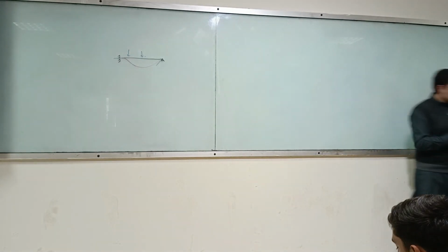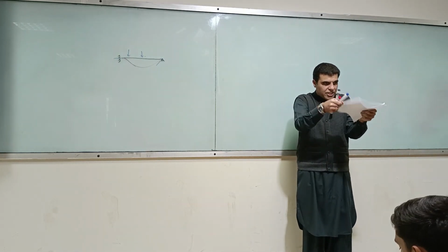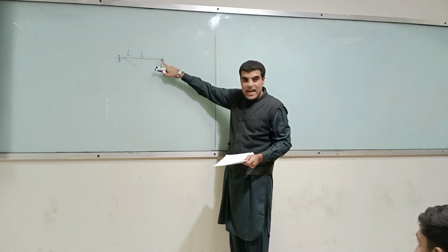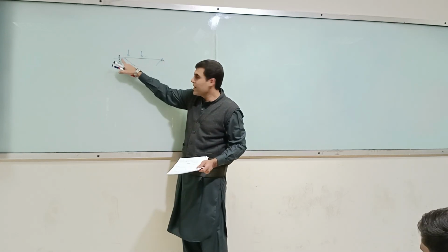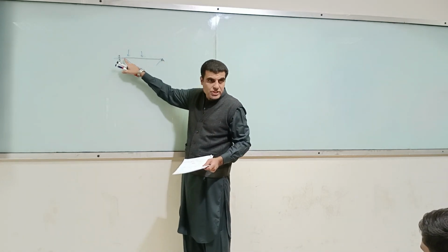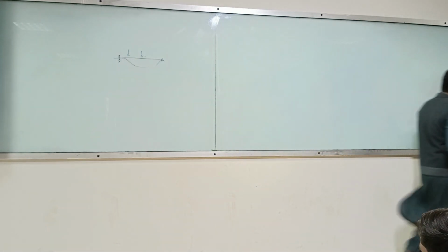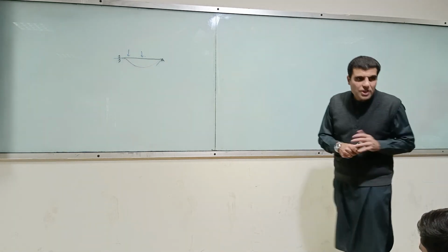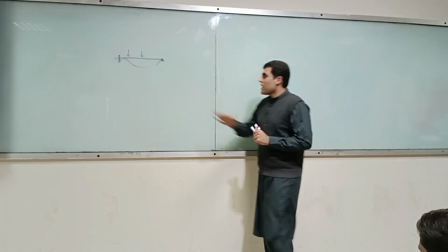So this is like I have held this tightly in this hand, so I don't allow any rotation. But this is rotation. So this rotation is allowed. So over here we will have deflection 0, but there will be a finite rotation. And over here we will have both deflection and rotation equal to 0. So using this property, you can develop another compatibility equation and you can solve your unknowns. This you will do in detail in structural analysis 2.